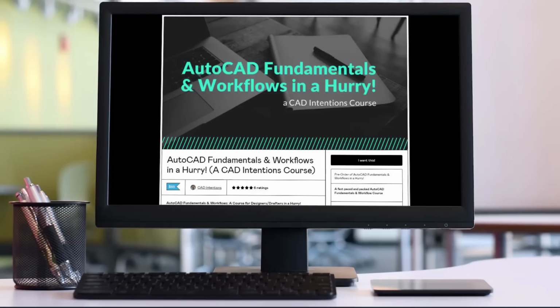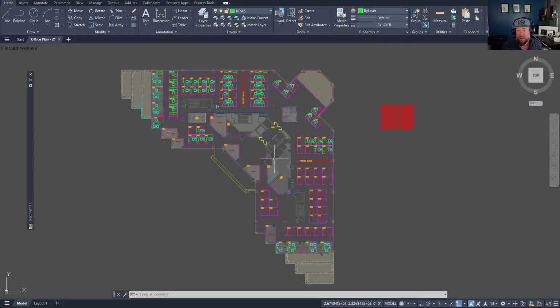All right, let's move on to tip number 6. All right, so in this one, we're looking at the LAYWALK command. So you can activate that up top here under the layers flyout, and it's got little shoes looking like it's walking, or you can simply type in LAYWALK.